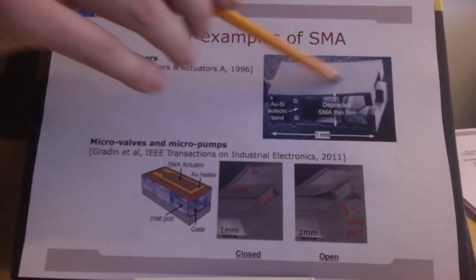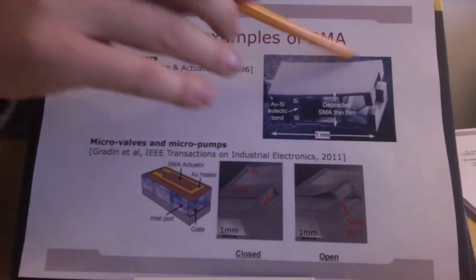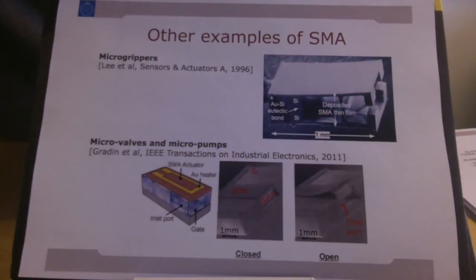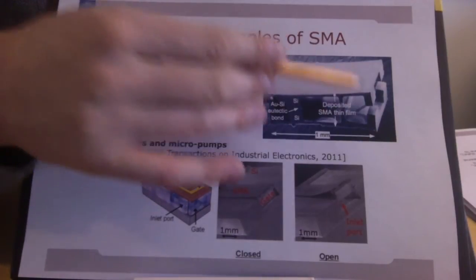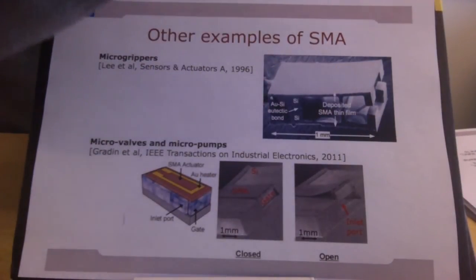And on both the top side and the bottom side, there's a thin SMA layer deposited. The position of this thin SMA layer causes a stress. So when cooling, so you deposit at a hot temperature, and cooling, you actually get a bimorph between the SMA and the silicon, and the whole structure will be stressed and be pulled open.